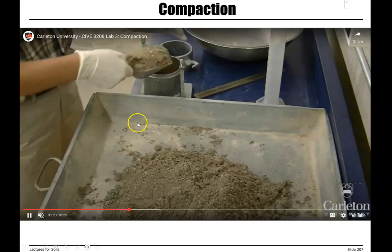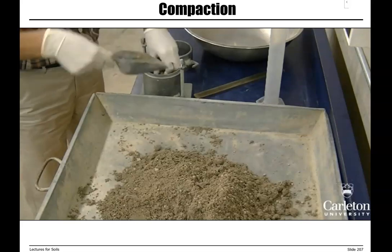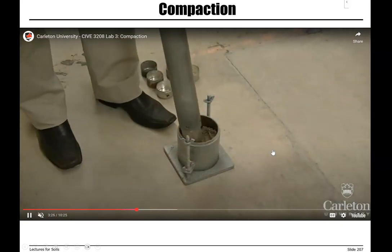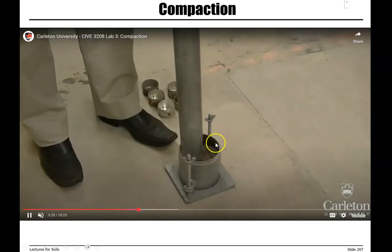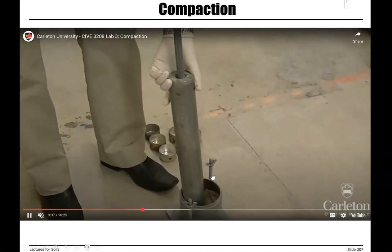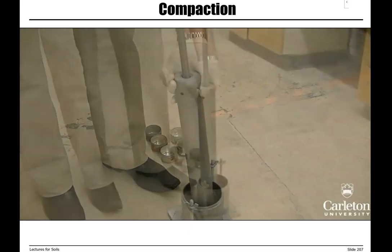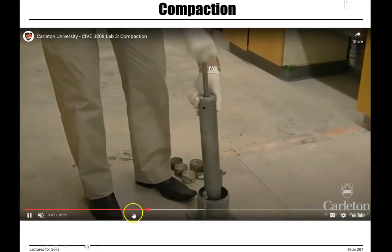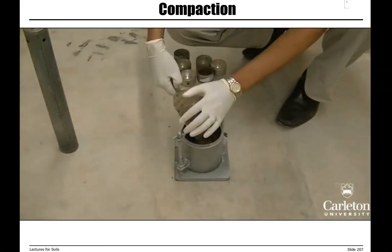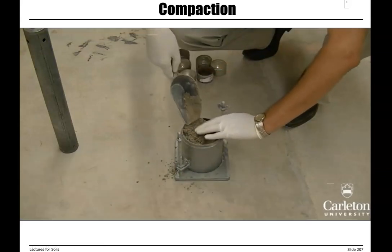Put first layer of soil in the mold. Use the hammer to compact soil. Make sure that you move your hammer around the surface of soil to have a uniform compaction. This is the first layer, 25 number of drops. Then you add more soil and do the compaction for the second layer.